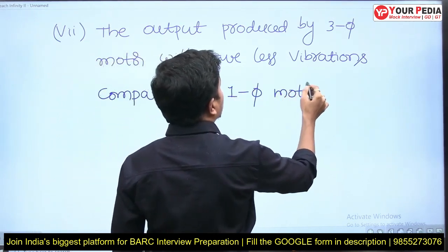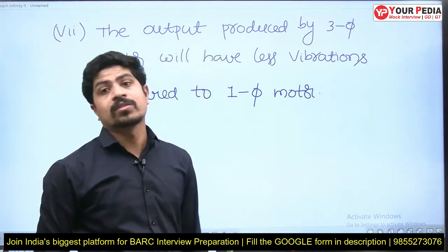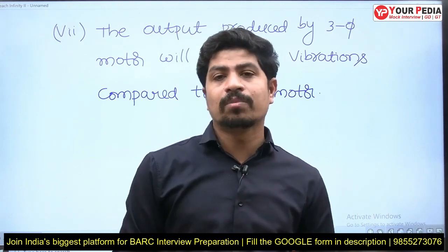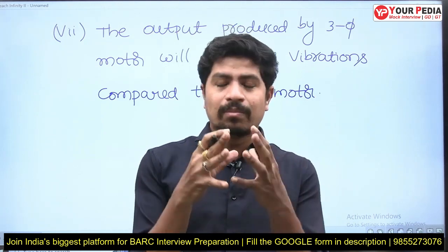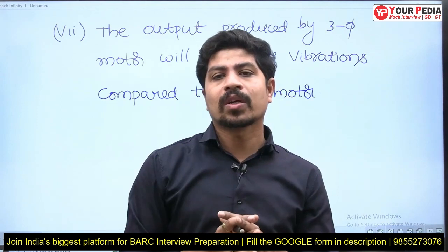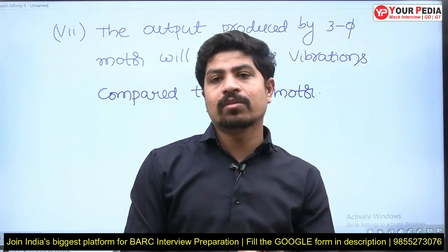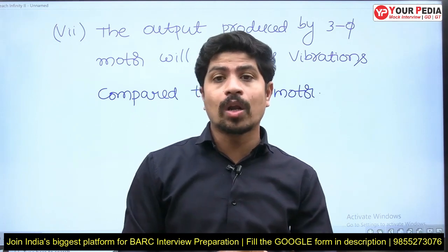The single phase one will create a lot of vibrations. If vibrations are more, then the life of the machine will decrease because of vibrations. The machine parts will get loose, and it requires frequent servicing of the machine. All these are the advantages of three phase over single phase.